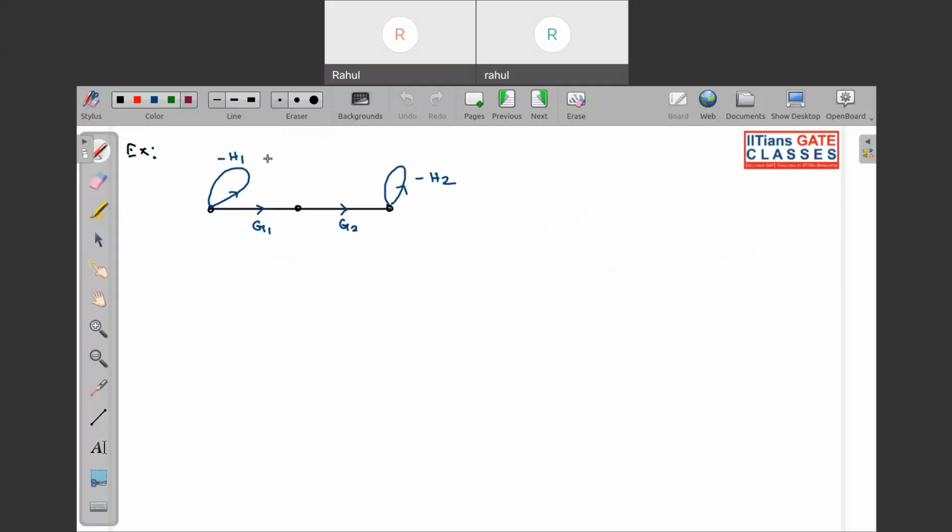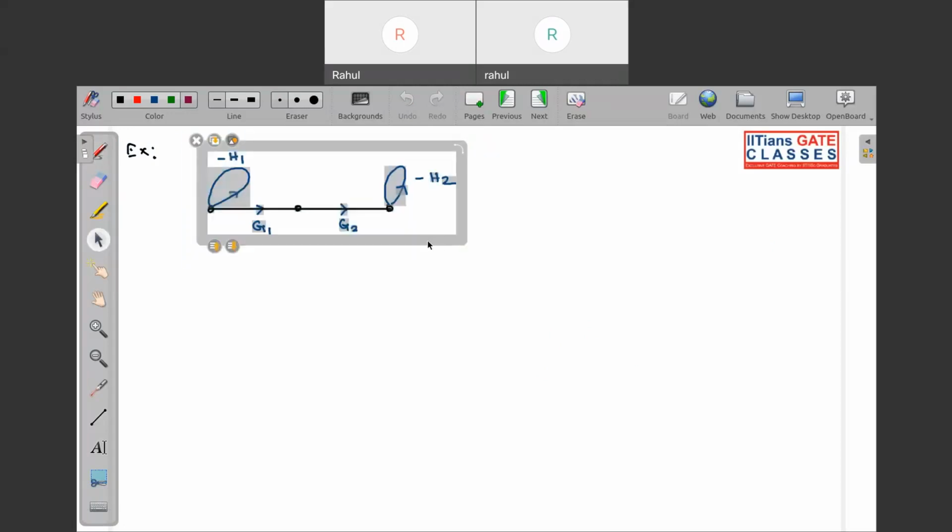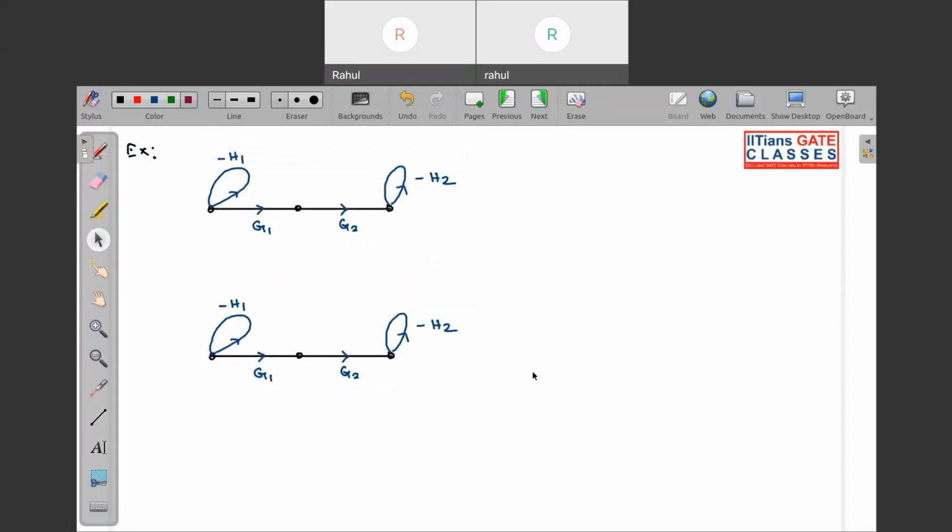So now over here we have one question. I want you to calculate this. So very quickly do. So you can see over here that we have one self loop at your input node. So this is R, this is C. So for calculating the transfer function, I need to remove this, because we have already discussed that a self loop at your input is not possible. Okay, so we will remove it.